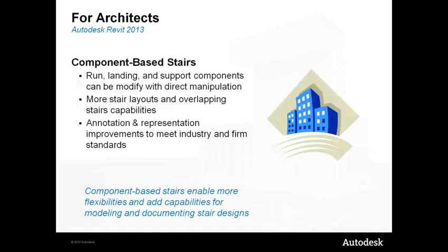You can create multiple runs and have Revit automatically create landings to connect the runs. The Run Component tool provides support for precast concrete stairs with the ability to customize end conditions such as notch and straight cut for stair runs.